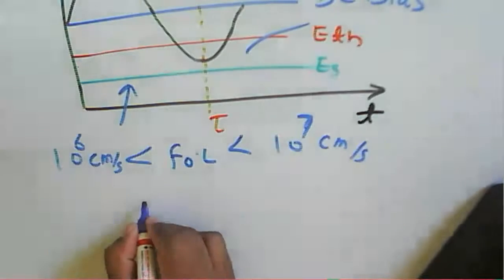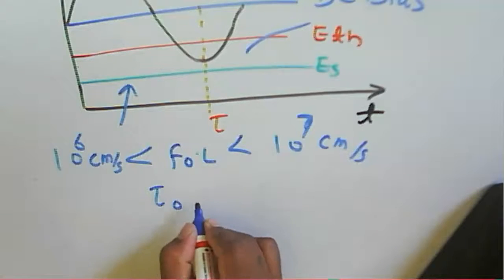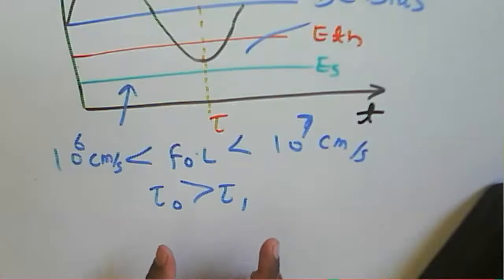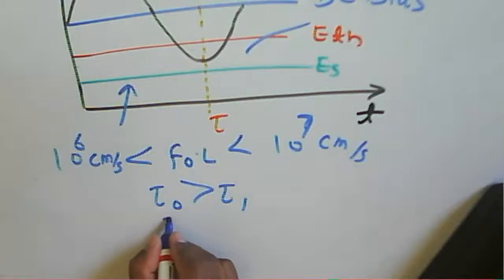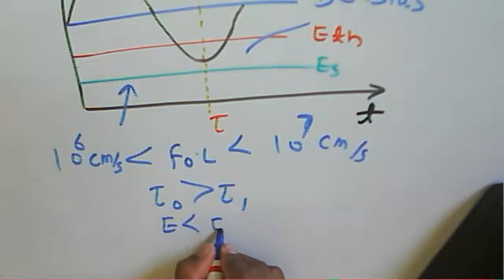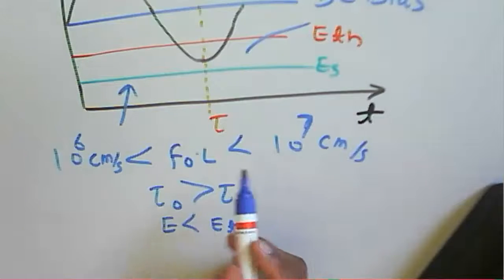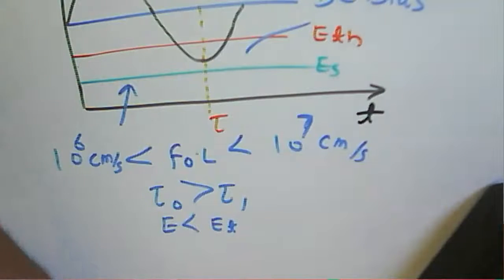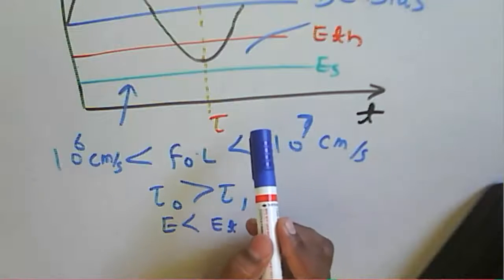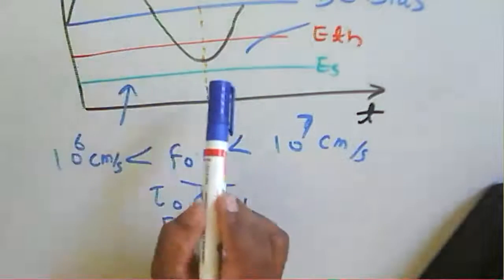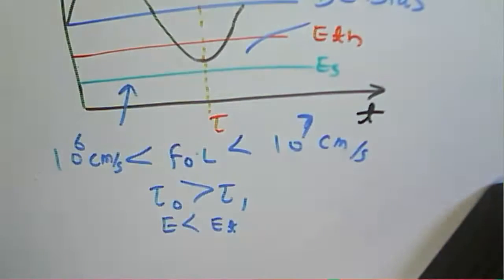And the transit time is supposed to be chosen greater than this. At that particular point, the domain is collected at the anode, and the field here we're supposed to consider E is less than ETH. So that is what we can say about the delayed domain. Why is it called a delayed domain? This domain forms only after the field value again rises above the threshold value there.